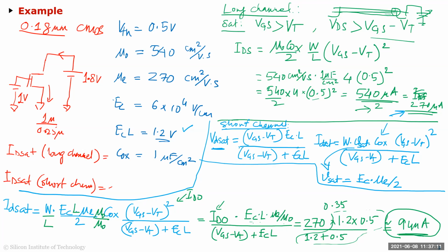If you just know that, they're not going to ask you what's the mobility degradation equation. Even if they ask you and you fail, they're not going to hold it against you. But if you say, yes, the mobility is going to degrade and be a smaller number, it could be as small as half, and your electrons are going to saturate earlier than your predicted VDSAT before, most people will be very happy with that answer. They'll know that at least you understand what's going on with the short channel.